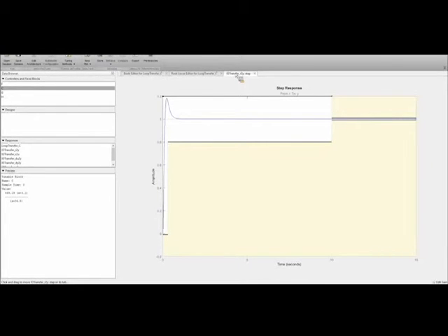Because with lead control, you're always adding, so all these metrics in terms of windowing out the complex plane and saying, all right, this pole location will give you this step response, that's for a second order under-damped system. Even if we had a system with just a single pole, the lead is going to add an extra pole, so we have the potential to be second order under-damped because it has 2 poles. But we've also added a 0, right? So it's always going to have an extra 0, and so it's going to be slightly off that.